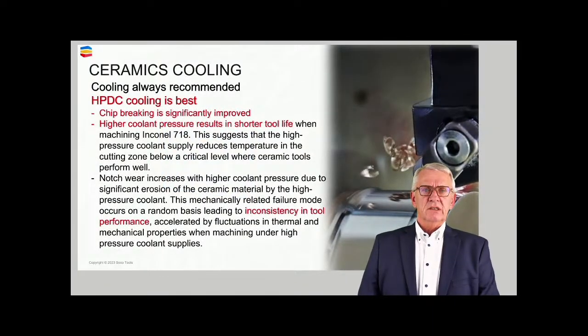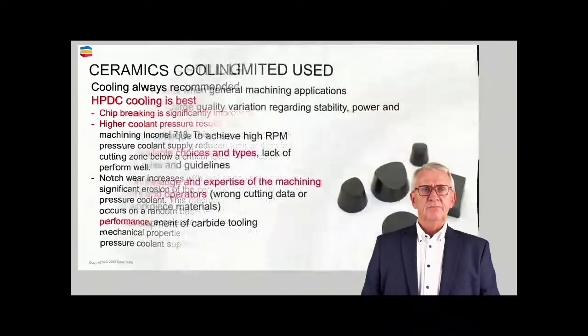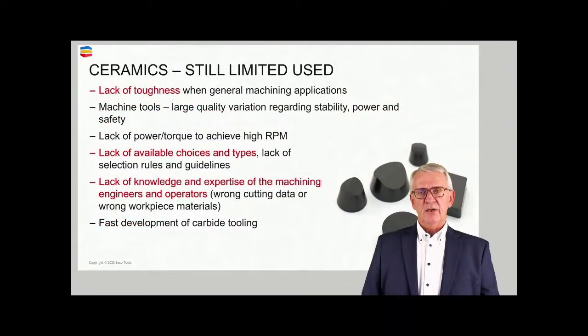Cooling is always recommended. HPDC cooling is best. That has a lot to do with the chip breaking. HPDC is the high pressurized directed cooler, what we call in SECO jet stream cooling.